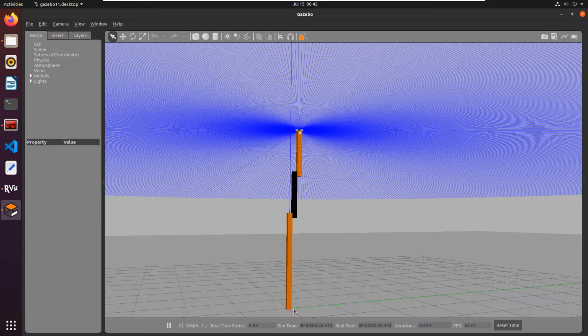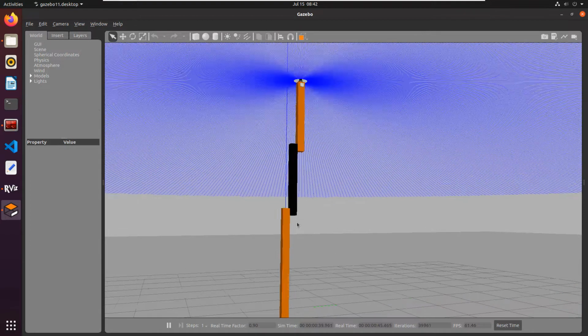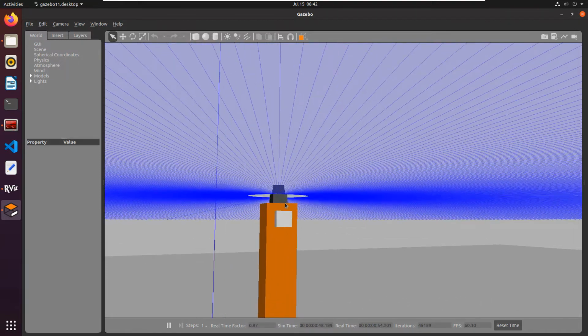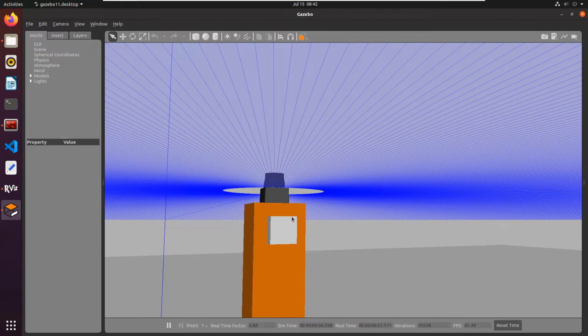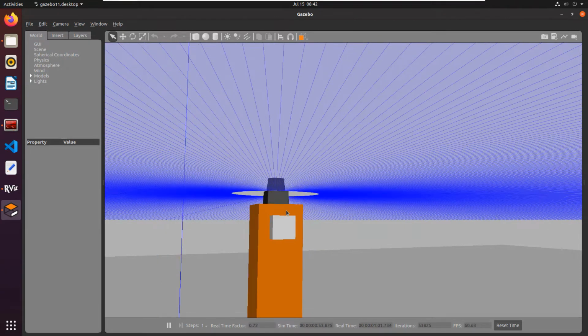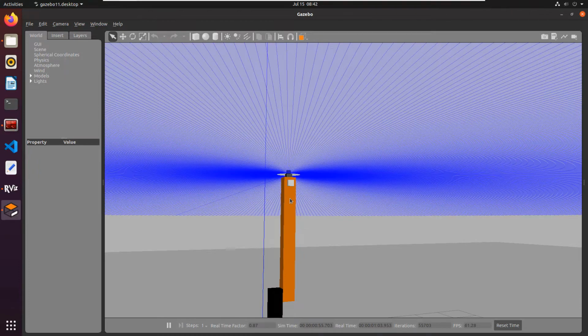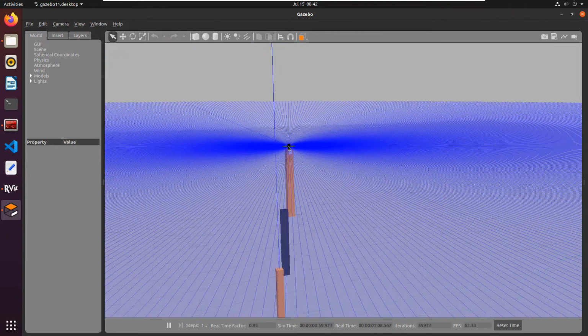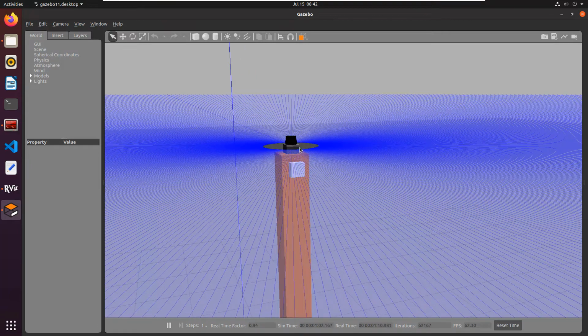on the bottom a fixed joint, with the world as the root frame. So the root frame has a fixed joint, and the next is actually a revolute joint, but for the demonstration they are providing a continuous joint. So 2 continuous joints, and then on the top these 2 sensors are fixed on this link. This is the simulation, and we can discuss how to attach these sensors.